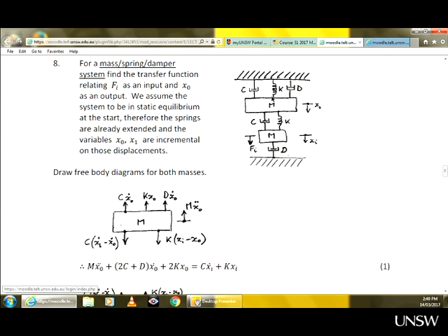So for this one, you eliminate all other components and substitute them with appropriate forces. So here, obviously when the mass moves down, you will have a force acting against the motion of the mass. In this damper, the force will be proportional to xo dot, because the other end is not moving.